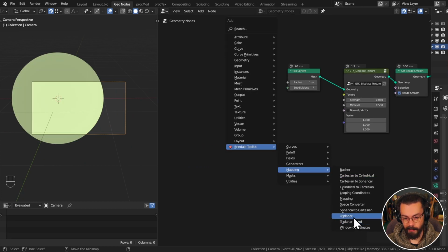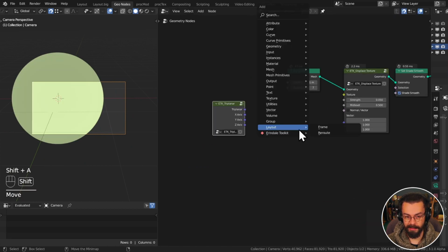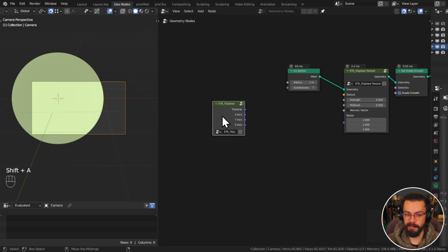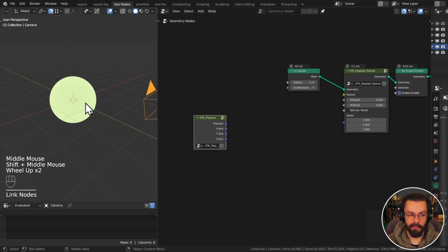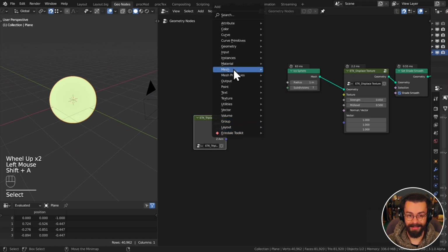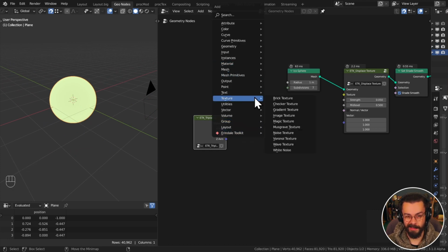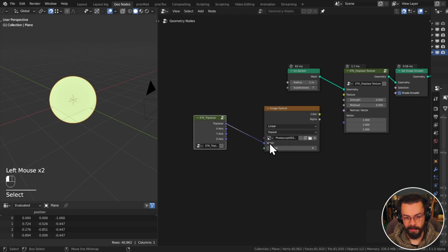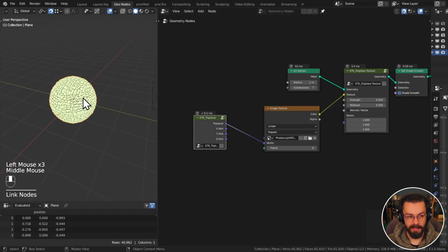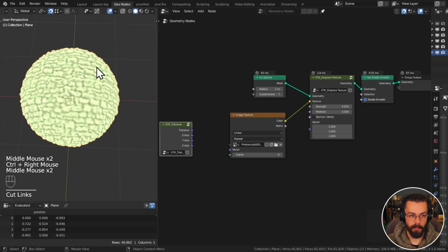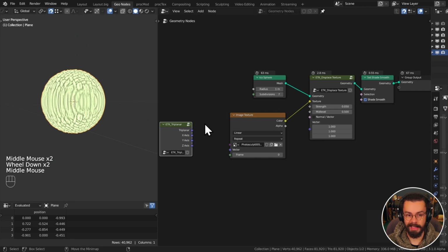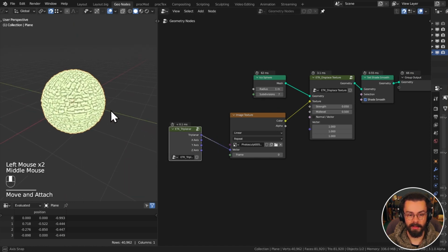Let's have a look at the next one, triplanar and triplanar blend. These are kind of a pair. You don't need to use them both. You can just use triplanar. Triplanar is very useful if you have something like an image, which is a two-dimensional texture. So let's bring back that image once more. If I bring in triplanar here into the texture, you can see that rather than this just being projected from the z-axis where you get this stretching, triplanar allows you to do box mapping.